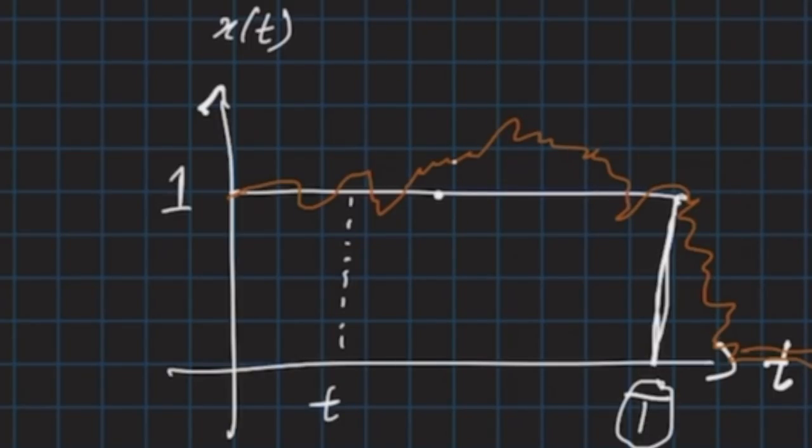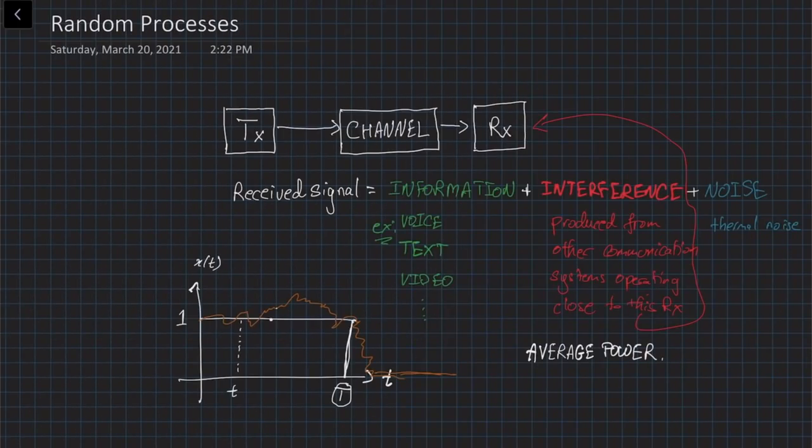Now, this might sound like I'm going to receive a completely random signal, and I'm not going to know anything about the signal. That's wrong to say. The reason is that it is possible to describe the signal in terms of the so-called statistical parameters of that signal, such as average power and the PSD, the power spectral density of the signal, as we will show further on in the coming lectures. Some parameters of the signal might tend to be more consistent to deal with: average power and PSD.